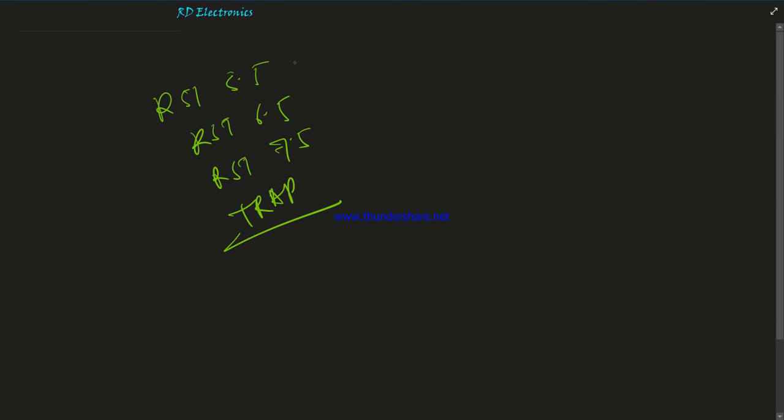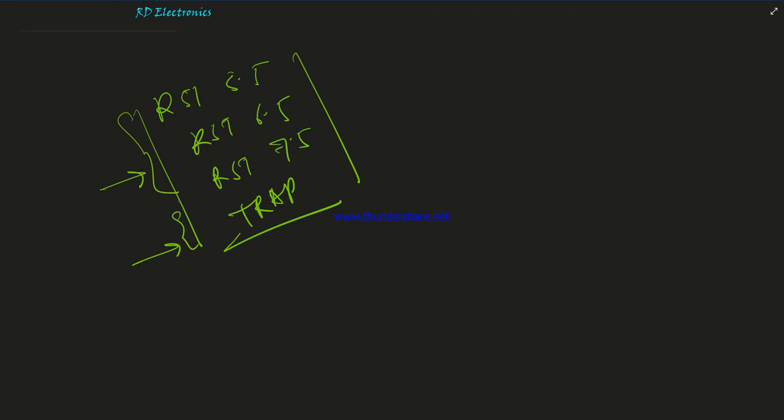Of these interrupt pins, the RST 5.5, 6.5 and 7.5 interrupts are called maskable, because they can be disabled or enabled by using a software instruction, but TRAP cannot be disabled until the microprocessor is reset. The last 4, the RST pins and the TRAP instruction, are automatically vectored or transferred to specific locations on memory page 00 without any external hardware requirement. They do not require any INTA signals or an input port, and the necessary hardware is always implemented inside the 8085.